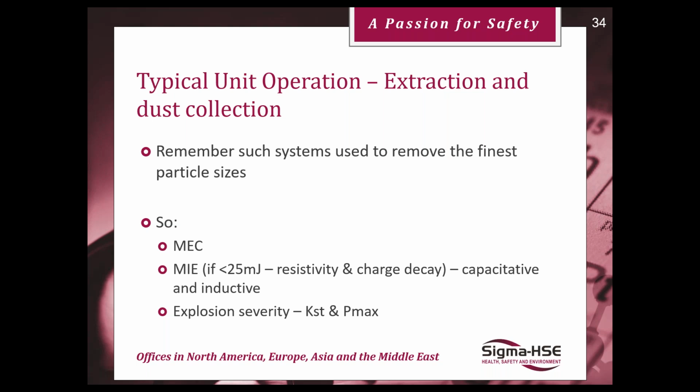The minimum ignition energy is important because if it's metal equipment, it could become charged if it's not correctly earthed, and the lower the minimum ignition energy, the easier it is that your powder's ignitable. The solution is understanding what the minimum ignition energy is, and then making sure that everything that can be earthed is earthed to take away that charge.